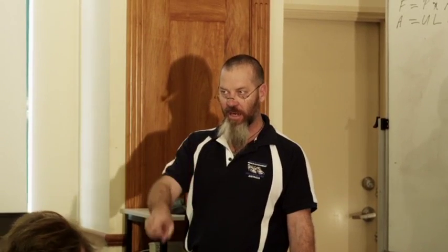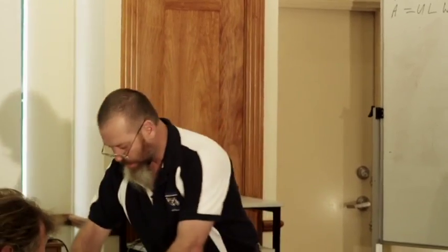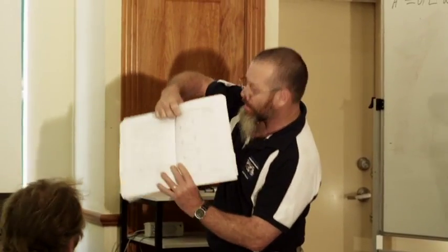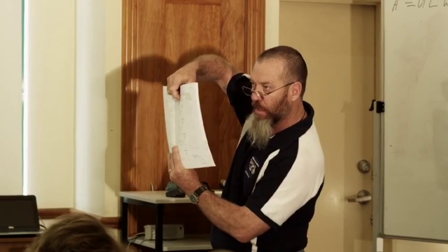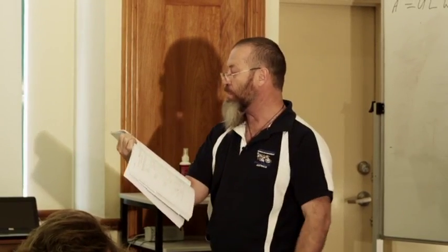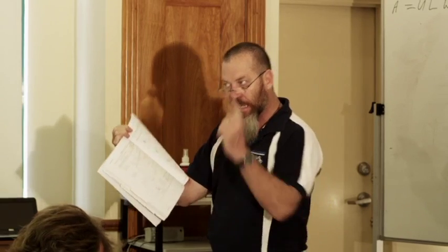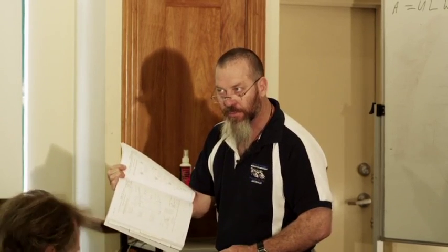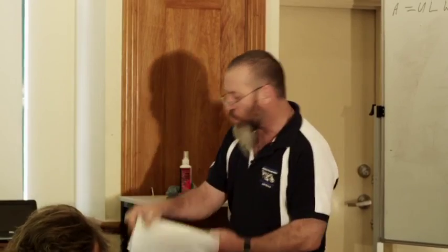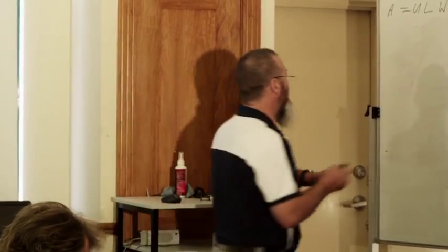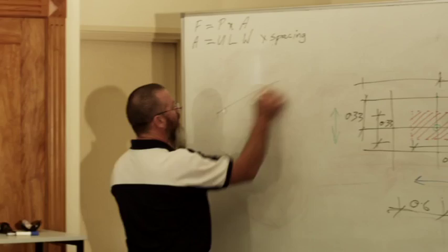But if I was smart enough to read the next part of it, see there where my finger is, that little line there? What it says in my new book, it says rafters to beams, lintel, ring beams and veranda beams. It doesn't say rafters to top plates. All right? Now what that's about and why there's a trap here, this is the side of my house.